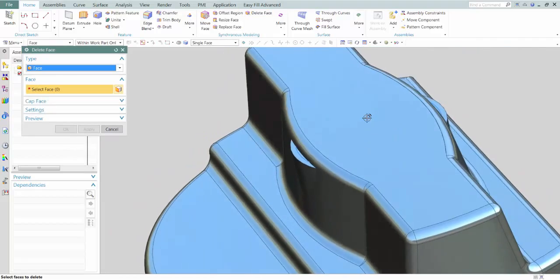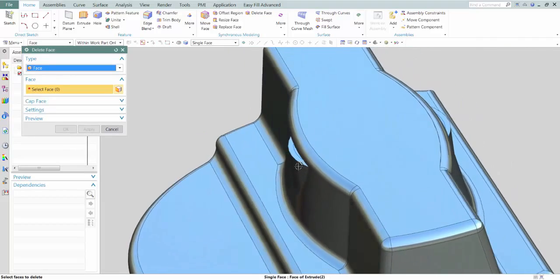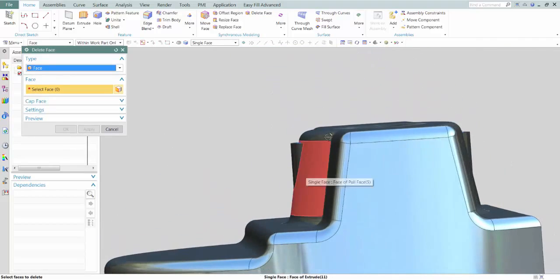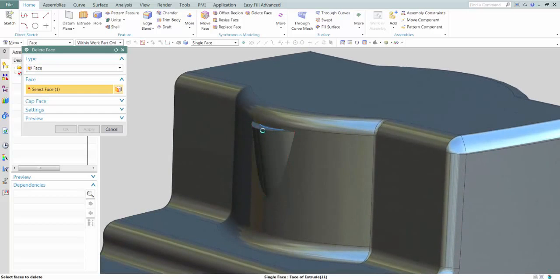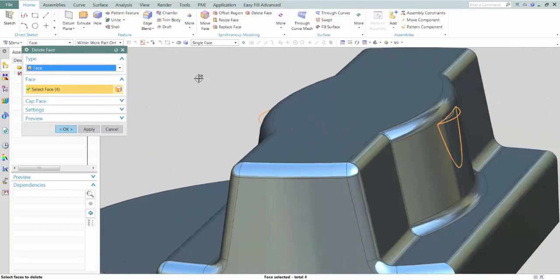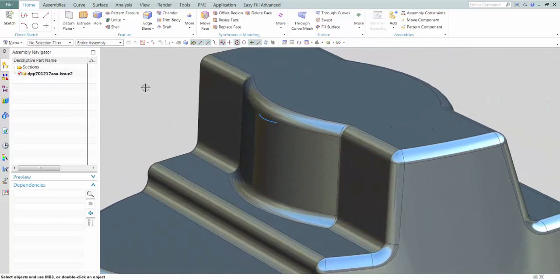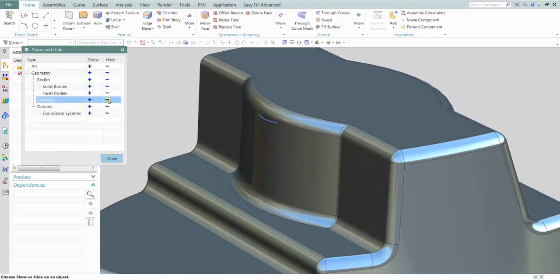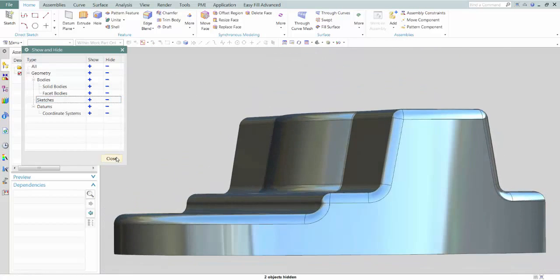And if I flip the model over, you'll notice that as I built that geometry, it actually extruded out of those walls because of that angle we had placed out there. Well, that's not a problem. We can just go in and remove that geometry. And this again is using our delete tools that are incorporated into the synchronous capabilities out there within our product.